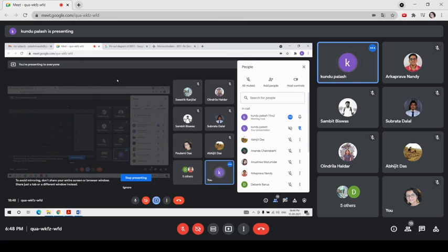So try to understand the timer operation. We have, to some extent, studied the functional description of the IOs. There are 4 IO ports, designated as P0 to P3. Each IO has a separate or different type of internal architecture, which I discussed in the last class. Similarly, you must go through the functional diagram of each timer mode of operation. Otherwise, you cannot program the timer for a given application.